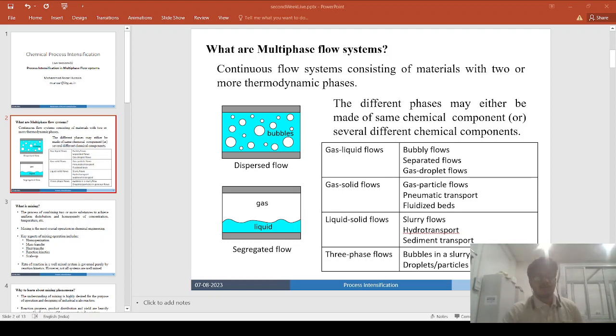Another example is the production of superphosphate used in manufacturing fertilizer, where hydrogen fluoride and silicon fluoride gases are vented from various points in the processes. Spray towers can also be used for odor removal in bone meal and tallow manufacturing industries by scrubbing the exhaust gas with a solution of potassium permanganate. So that is how you can perform the odor removal.